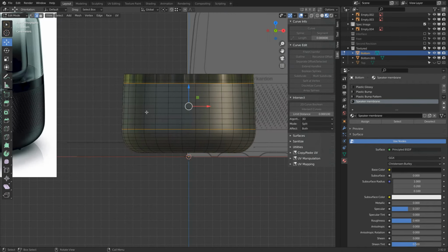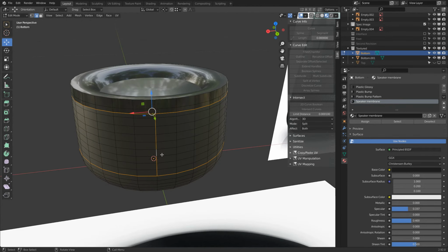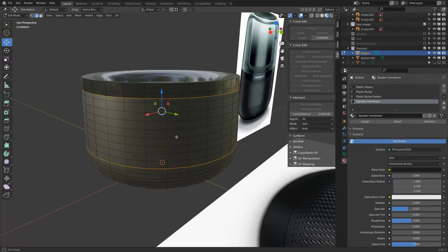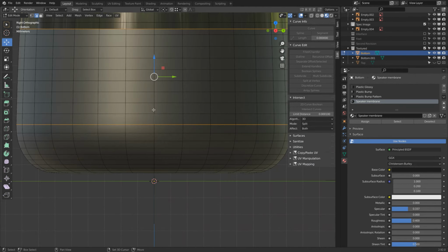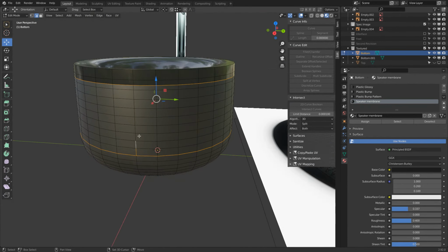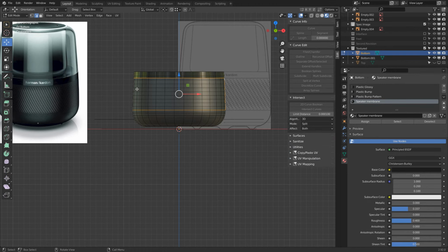Or if I go to the side, 3, yeah, I see here, there I have this line. Yeah, let's try that. C, middle mouse button. So I paint over it. Go to a side view and then simply adding this to there. Honestly, what I'm doing is really being super picky. You can just keep the back part, but this will be now here at the side.